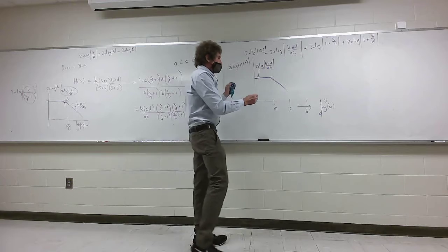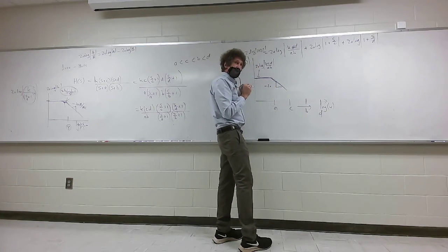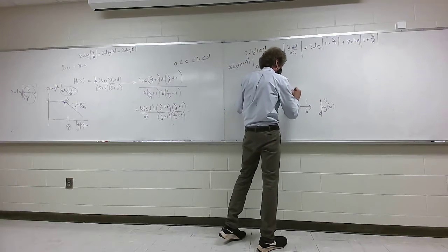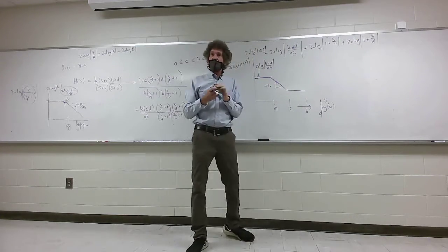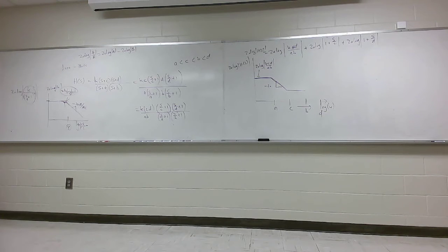But it was already decreasing at 20 dB per decade, so now it's just flat, isn't it, class? Y'all with me? It was decreasing, then it tried increasing at 20, it canceled the effect of decreasing. Real important you see that. Got that?